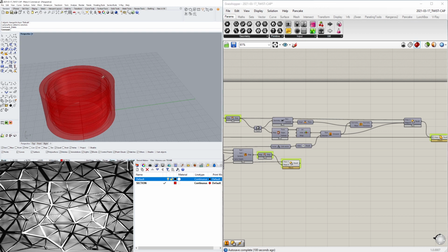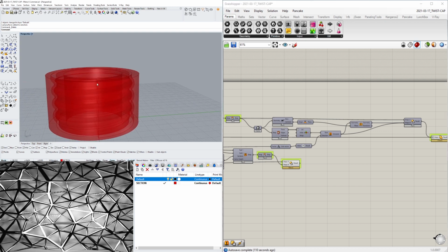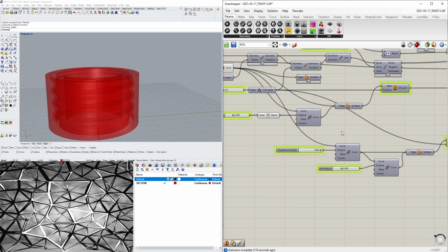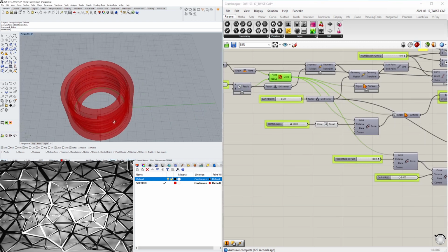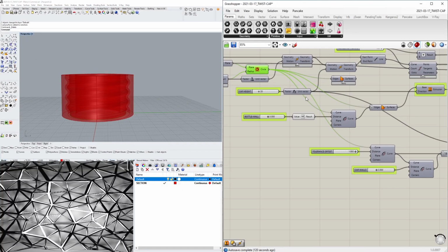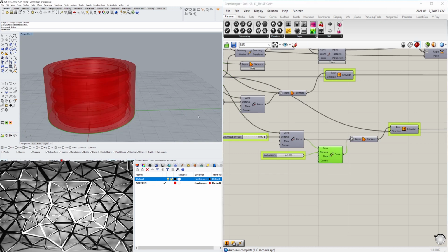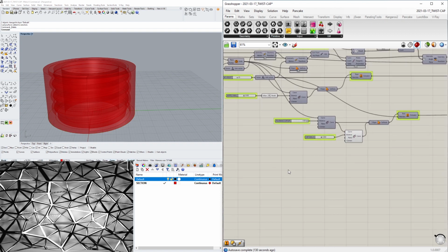Next step is going to be to create the top portion of it, which is going to be a circle at the top, extruded up. So let's go to our base circle, which is this one. And it's actually going to be the circle that we offset that's furthest out. That's going to be this one, that has the cap walls.